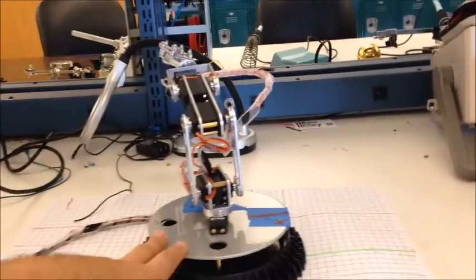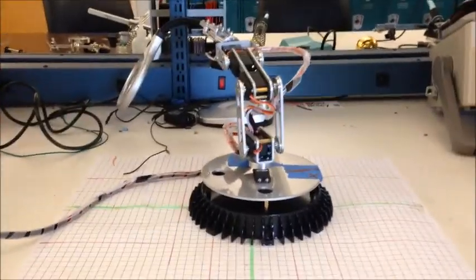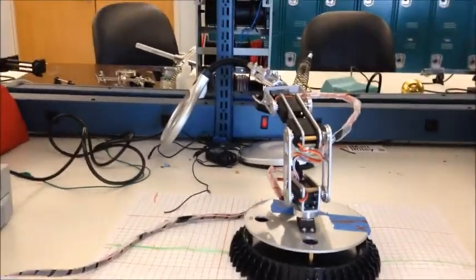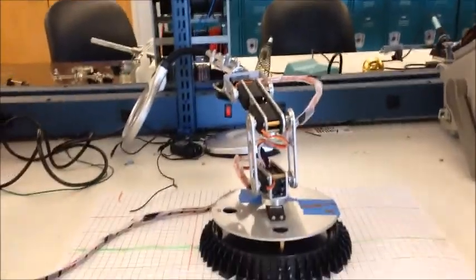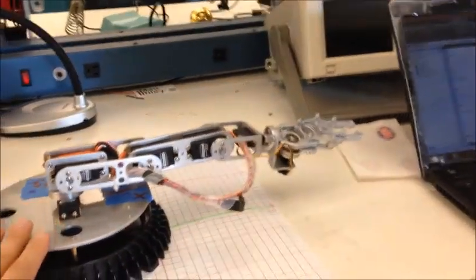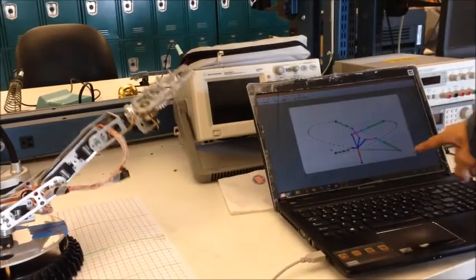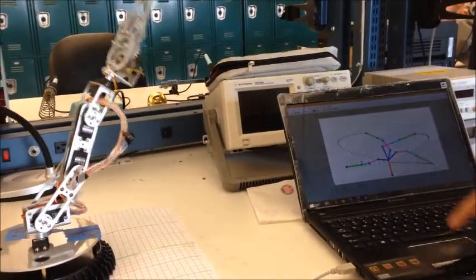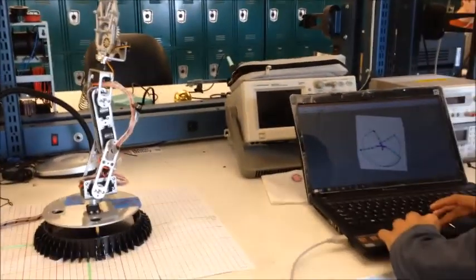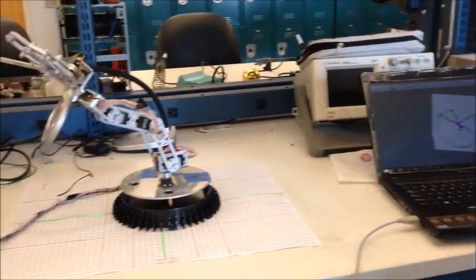Alright, so now for the final location, we are going for location 4, which is X equal to minus 27 centimeters, Y equal to minus 16 centimeters, and Z equal to 8 centimeters. There's location 4, and we will move again to position 0. And slowly it will start moving. So if you can see in the MATLAB simulation here, it marks the position by a pink colored dot, and then the robot moves towards it.